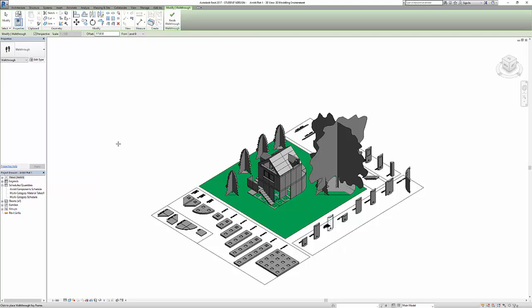First of all, click with your first position. You will see that the camera is pointing in a certain direction. What we're going to do here is click multiple times and approach the building, walk alongside it and then away from the building, and then instantly approach it back from the other way. In this manner I can create a walkthrough that really focuses on the build.